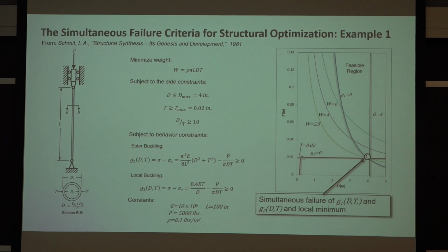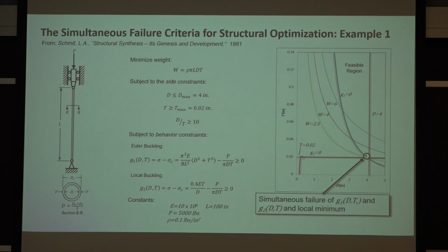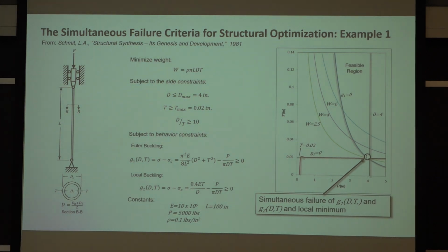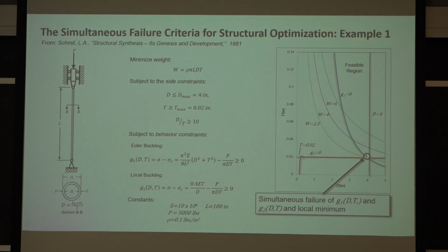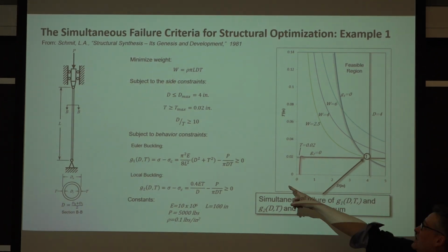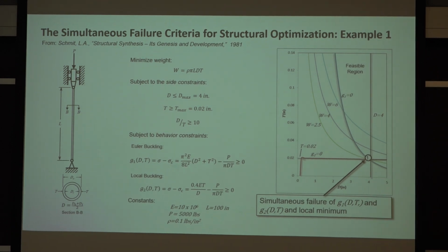point number 1. What I want you to really understand about this graph, because it is going to be important in our next lecture, is that you've got a two-dimensional design space. You've got two variables that you can mess with in order to create the lightest solution that carries the load: diameter and thickness. You've got constraints. The constraints are the diameter of the tube, and you don't want it to buckle, so that's the other constraint. You've got G here. You can think of plotting out these constraints on top of weight on this two-dimensional design space, which very quickly leads you to a solution. The lightest weight solution is right here at number 1.